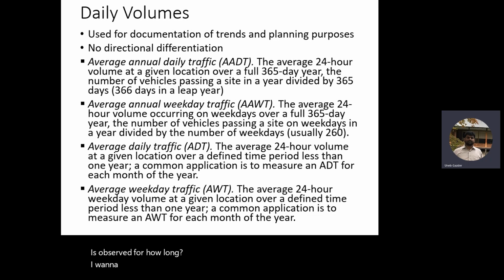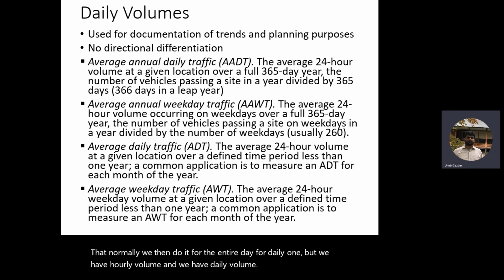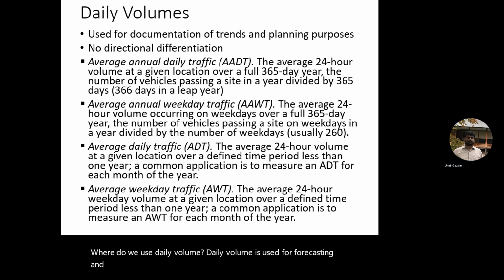1 hour more, right? Now 1 hour, that will be hourly volume. More than normally we then do it for the entire day, so daily volume. So we have hourly volume and we have daily volume. Okay, so we'll start with the discussion of daily volume. Where do we use daily volume? Daily volume is used for forecasting and planning.